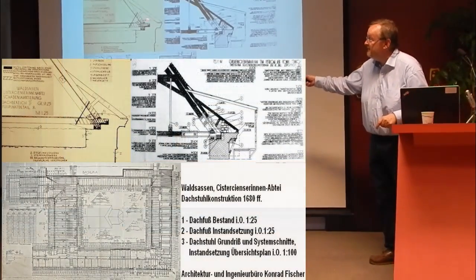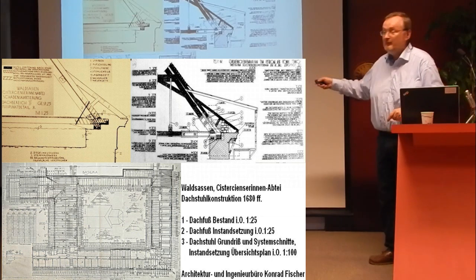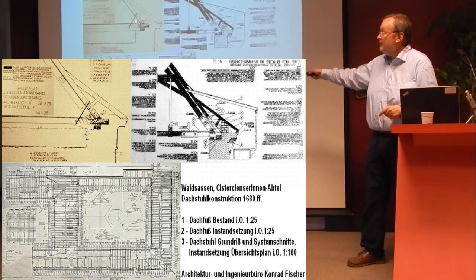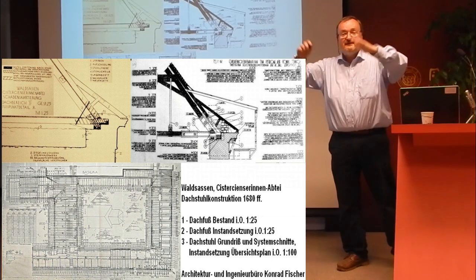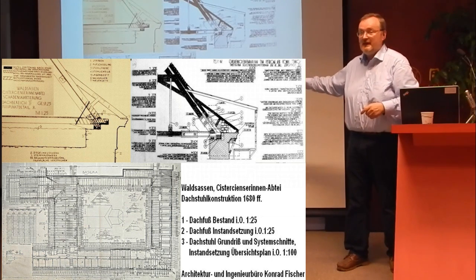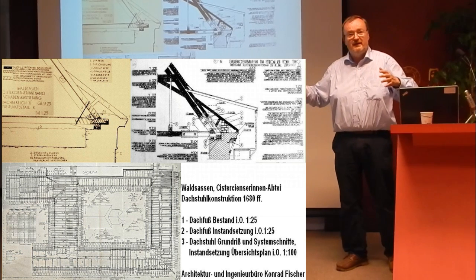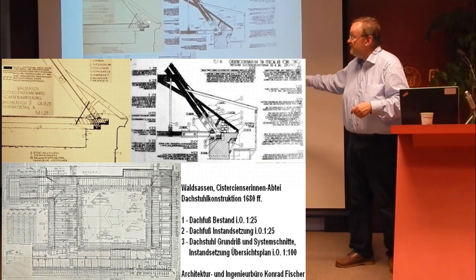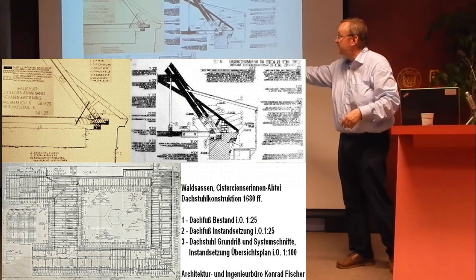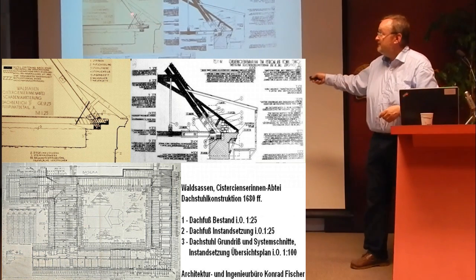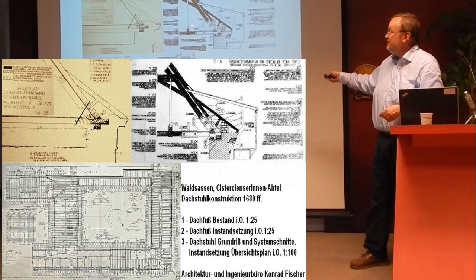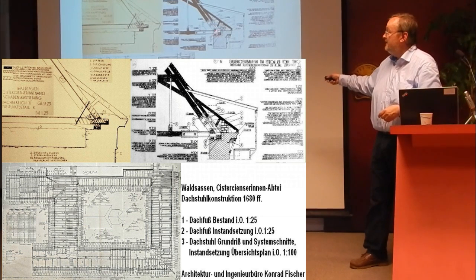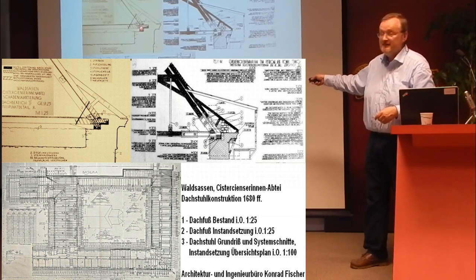You can imagine maybe here. The whole situation was rotten. Why? Because the timber work was done first to get the tiles on it and to can, in Baroque times, build under the roof in a dry situation. And then comes the masonry, and they do here a counterweight to get rid with the overhanging cornice. This part of the facade. And that was a given situation. And that's a repair, some new wood, and a new counterweight which will not anymore inbind in the wooden construction.